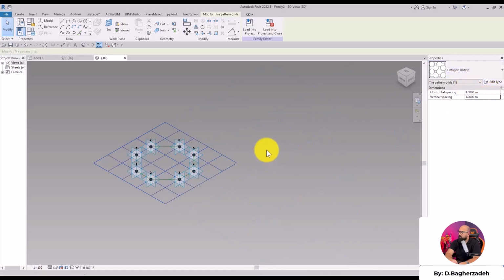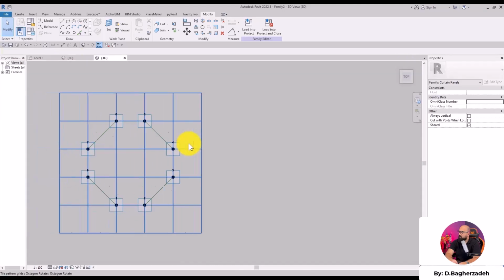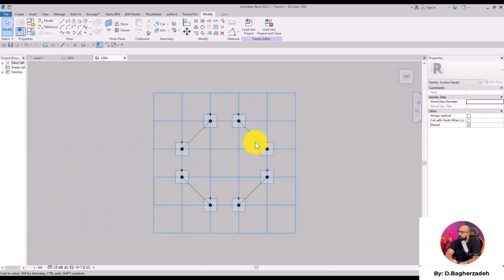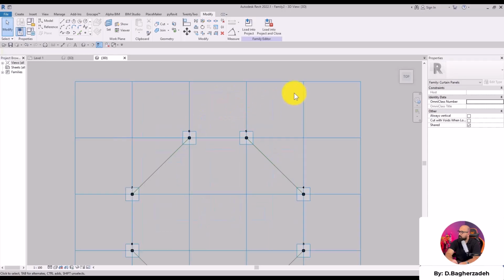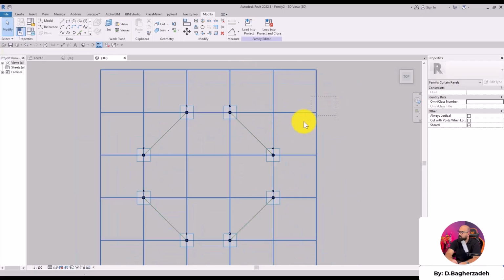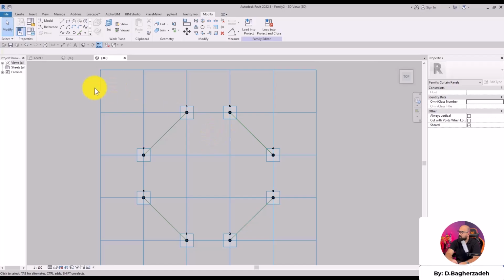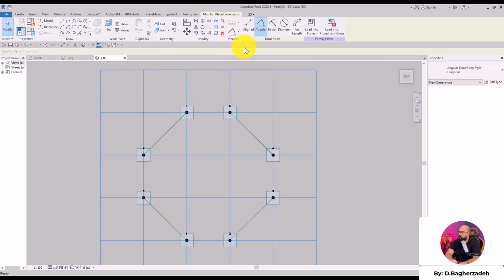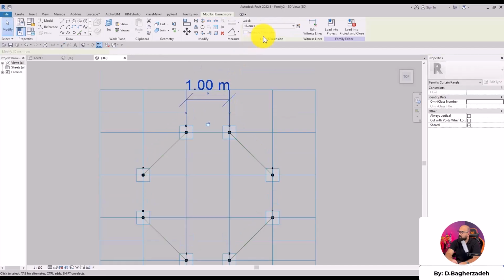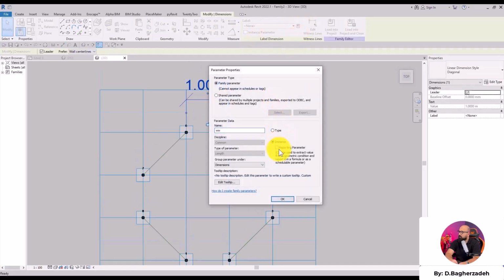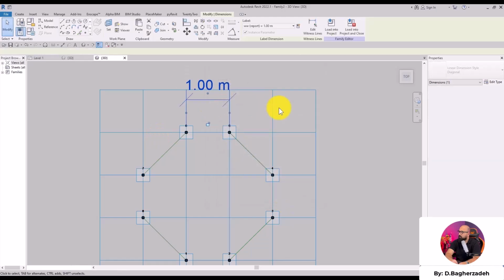Now guys, what we need to do next would be creating the form that I mentioned. I mean, that bend symbol form that I said. And also we're going to get an extra part right up here, in this cell here, that we need to work on. So guys, to understand how exactly we're controlling the size of this pattern, for example its width, we need to set a dimension here. Then right after, we need to create a parameter called W. It'll be an instance parameter and also a reporting one, okay?